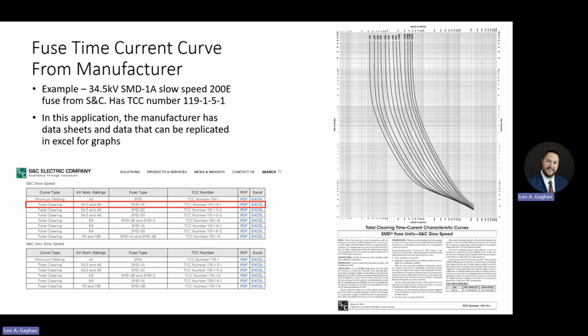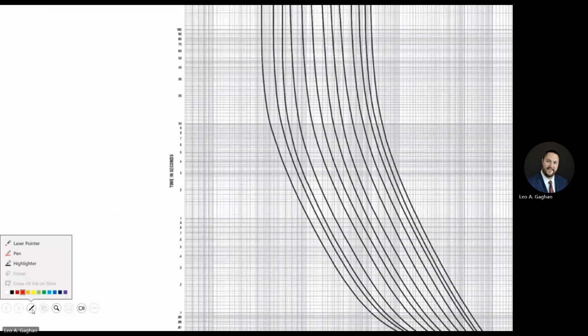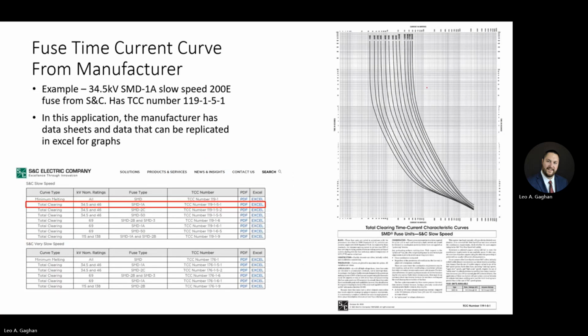I know it's tough to see. I tried to zoom in, but I didn't like it. But let's say we had an intersection point in this range, where that looks like the intersection will go up around maybe 70 seconds. I mean, we gave that fuse 70 seconds. That was plenty of time to operate.